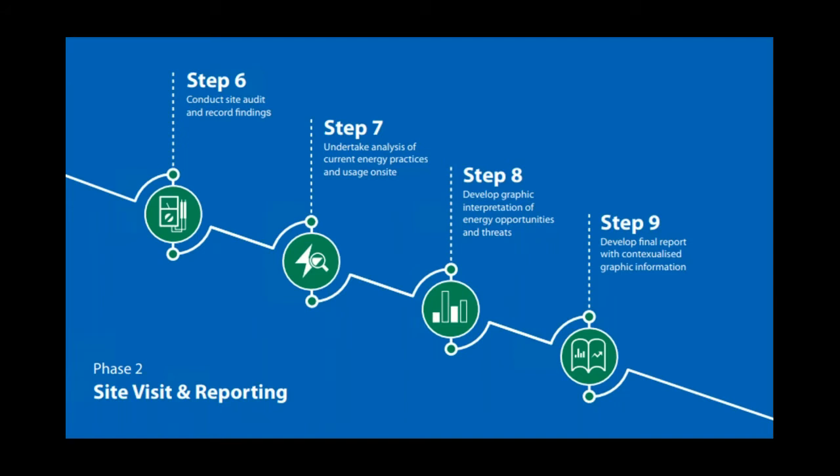So the building would look at getting the measurements taken by the energy auditors, and site visit along with reporting is this phase 2, where the initial step would be to have the site audit measurements taken. Then after that, we would understand how the building is operating. We would analyze the different energy practices already employed across the building, or if not, what are the practices they have planned, or what are the practices that can be implemented on site. So we understand the usage on site. This would be more tangible because we're on the field. We're actually seeing the reality of the systems, how they operated, how long they're operated for.